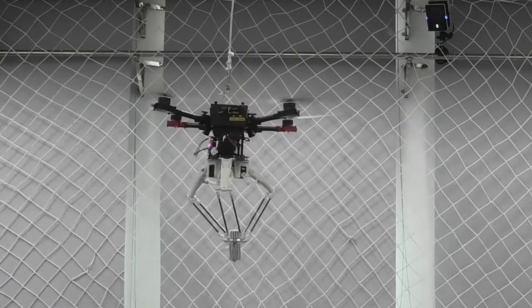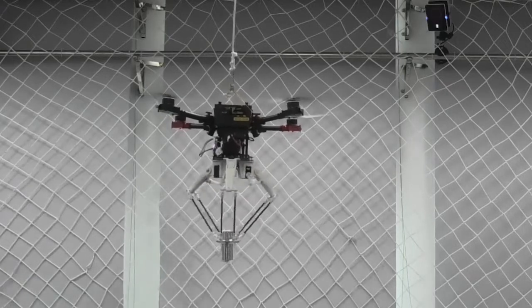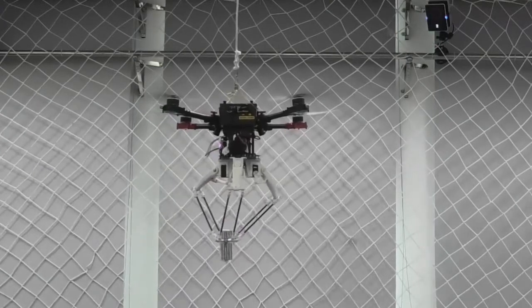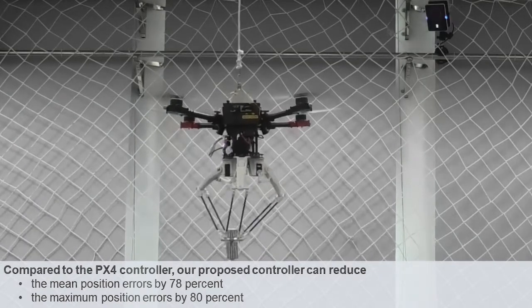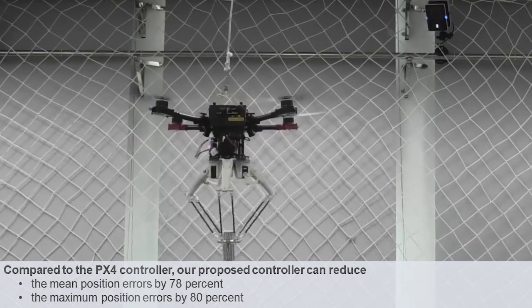The purpose of this experiment is to verify the effectiveness of the ESO and the flight controller. A PX4 controller is selected as a baseline for comparison. A payload of 1.2 kg is mounted at the end of the delta arm. The control objective is to maintain the position of the quadcopter base unchanged while the payload swings fast. Compared to the PX4 controller, our proposed controller can reduce the mean and maximum position errors by 78% and 80%, respectively.